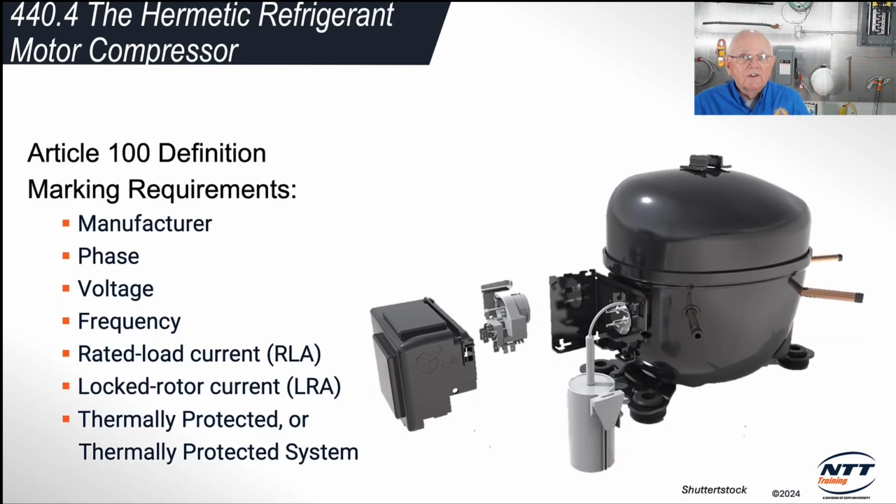First of all, there's a definition in Article 100 for the hermetic refrigeration motor compressor. And it's a little bit different. You don't see any shaft coming out of it. There are no shaft seals. The motor and compressor itself are actually inside of the refrigerant, all sealed inside of that one big black unit.